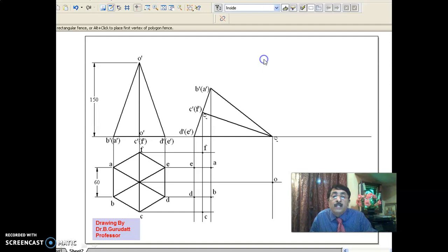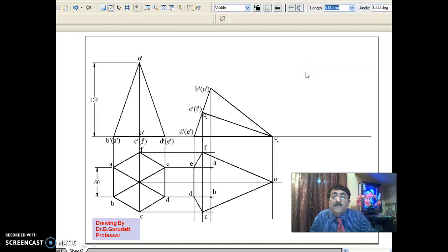Now, take the projectors down and complete the outer boundary of these points as the first step. Now compare apex with the base. Now when you are looking from here, base is exposed to the observer, base is nearer to the observer. As a result, base can be seen, darken the base. Now it is 6 plus 2, 8 edges are over. You have to complete 4 more edges. One is OA, one is OB, one is OC and OD.